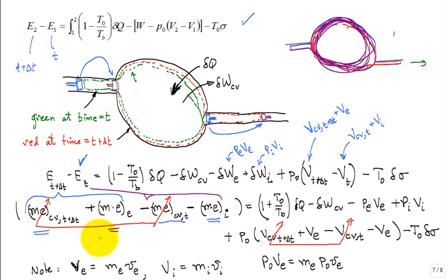What flowed out. Okay, and then I quickly expressed them as M times E, where E is our traditional non-flow exergy. Okay, then over here we work on this term. You say, I'm going to have it for a time increment delta t, have T naught and P be constant over the time increment delta t. This is just delta Q, how much heat is transferred, minus a little bit of shaft work, so Q in, a little bit of shaft work out of the control volume over the time step delta t.